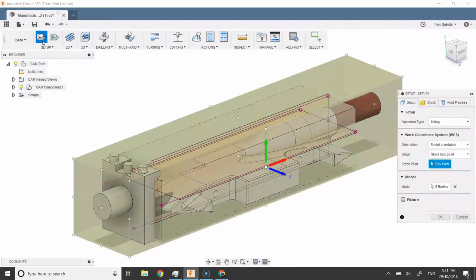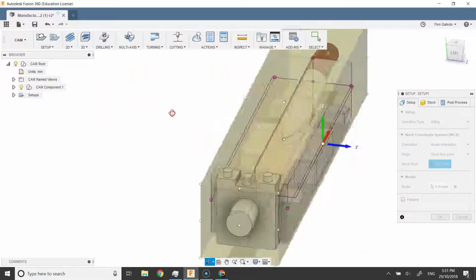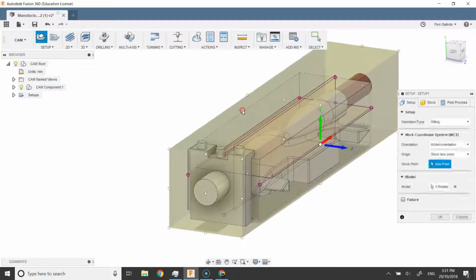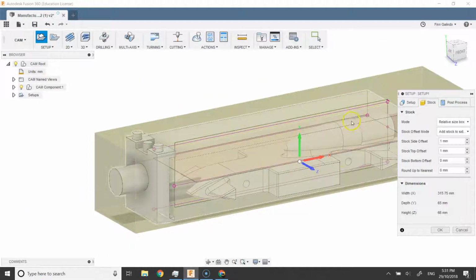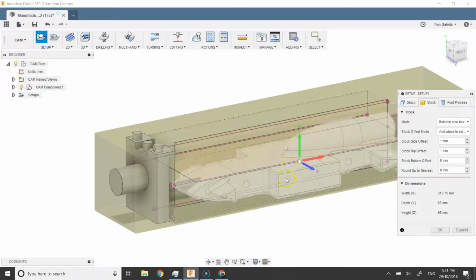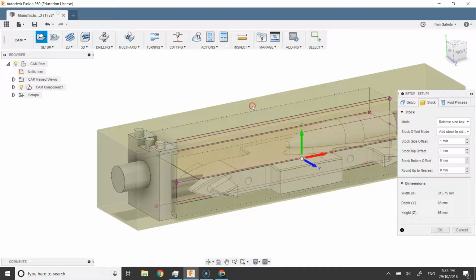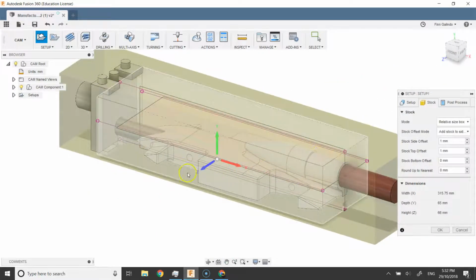So the setup, as the name suggests, is the setup information for our computer-aided manufacture process to use. So our robot, or CNC, will be using the information from this to then make the vehicle. Now the setup is really critical that you get right, because this is the bit that transfers the code into the right format so that our vehicle will be made in our machine. The basics are that we need to get the orientation correct and the fixture and body correct.